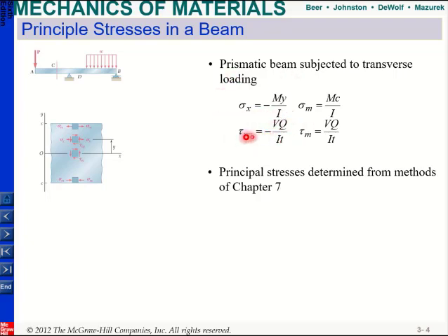What I know is, for example in this case, my maximum normal stress will happen at the ends, at the top side or bottom side, and my maximum stress is Mc over I. But for shear, my maximum stress occurs at the neutral axis and it's equal to Vq over It. So you just need to find the Q over this area, and then It.